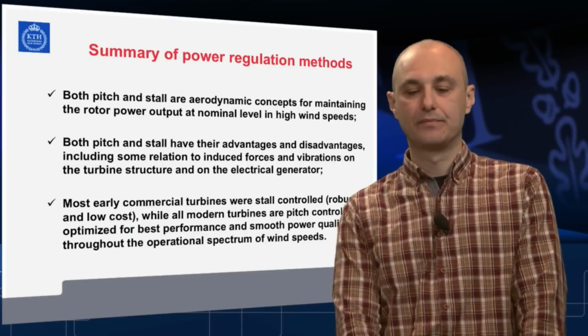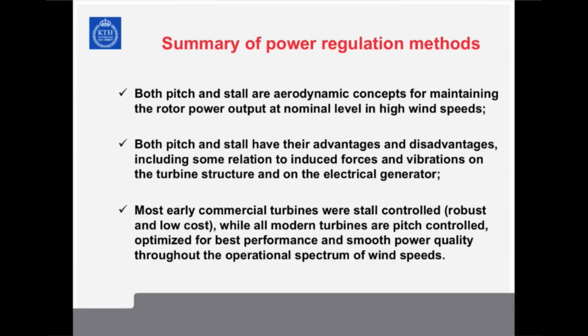Quick summary: both pitch and stall are purely aerodynamic concepts for maintaining the rated power output at high winds, using the fact that the aerodynamic performance of the rotor can easily be destroyed by changing the angle of attack. Both pitch and stall have advantages and drawbacks, of course, and the relation to induced forces and vibrations can be actually the most serious disadvantage for one or the other control method. Most early commercial turbines were stall controlled, simple, robust, low cost.